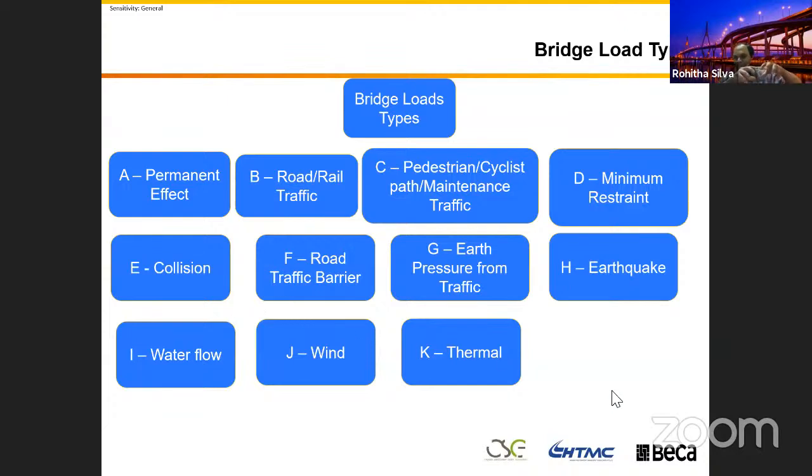You are designing a bridge on a local road or in a village area, right? Or you are designing a bridge on one of your major highways. That one is quite critical for commercial and other purposes. Let's say the bridge is linking the port. For your logistics, you need to make sure that link is functioning all the time. So then you can design for a load combination with the traffic and with the earthquake.